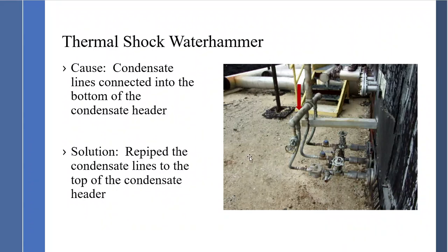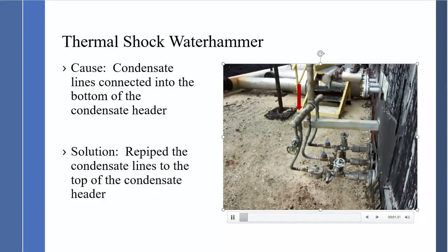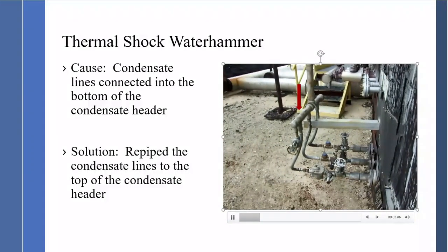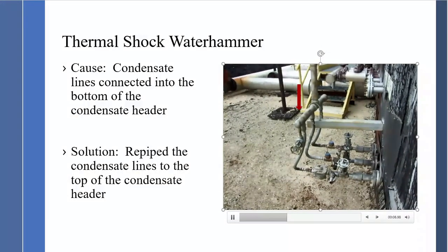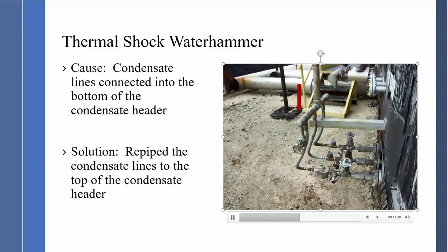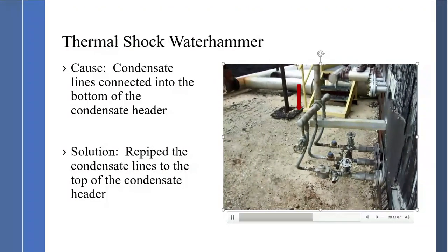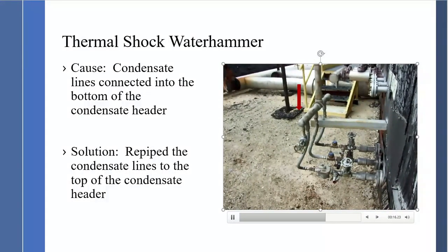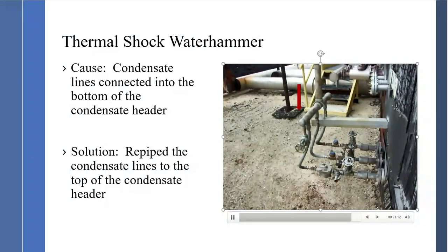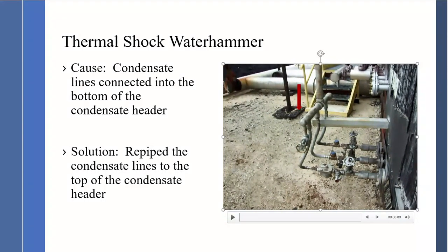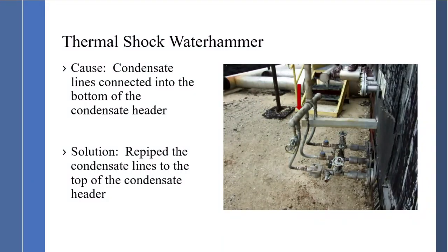Here's another video. This is connected into the bottom of the condensate header. Again, the same result. Again, the solution is to pipe into the top of the condensate header, and the Waterhammer will go away.